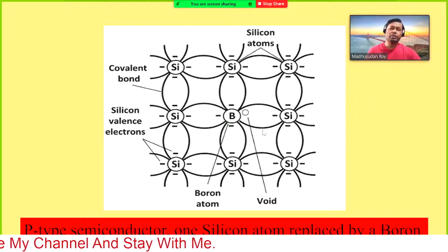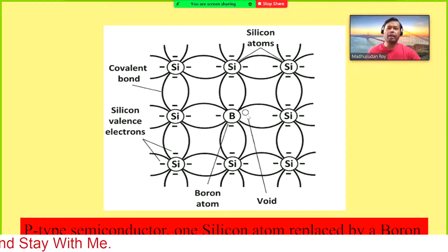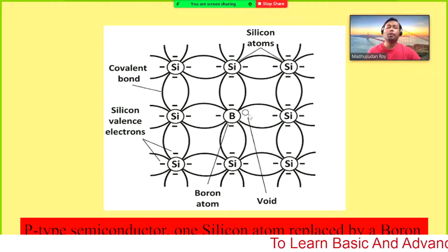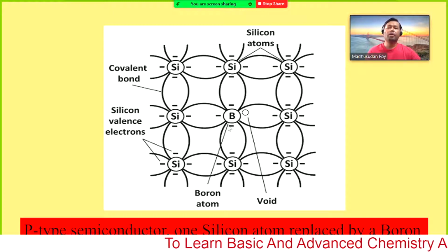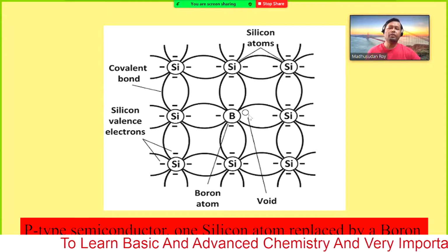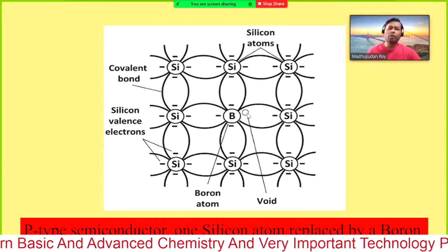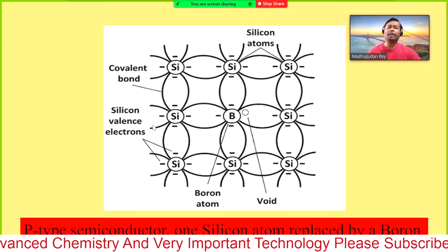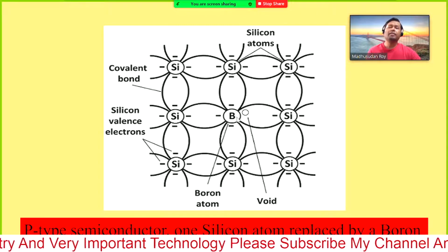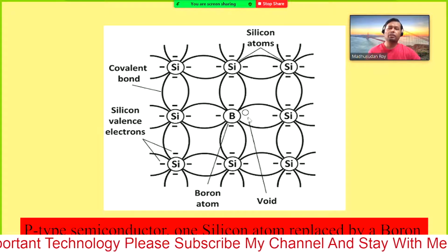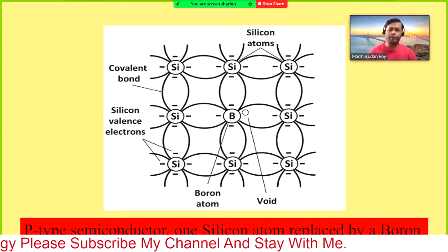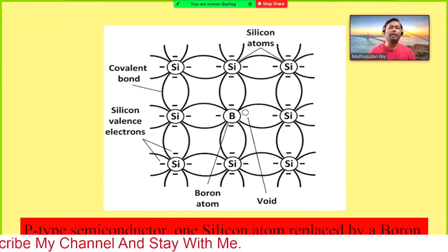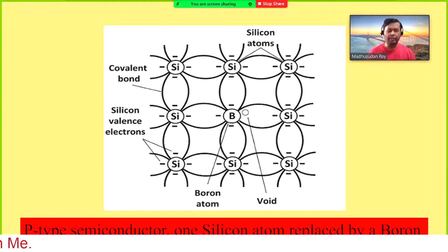that means when you apply electrons to the crystal, the electrons can come to the nearby free hole. Then boron would have 4 electrons, but boron cannot have 4 electrons because it has only 3 electrons in the outermost shell. Therefore that free hole will be transferred to the nearby atom, and that way the electron can be transferred. That is how we can prepare a p-type semiconductor and how the p-type semiconductor can conduct electricity or current.